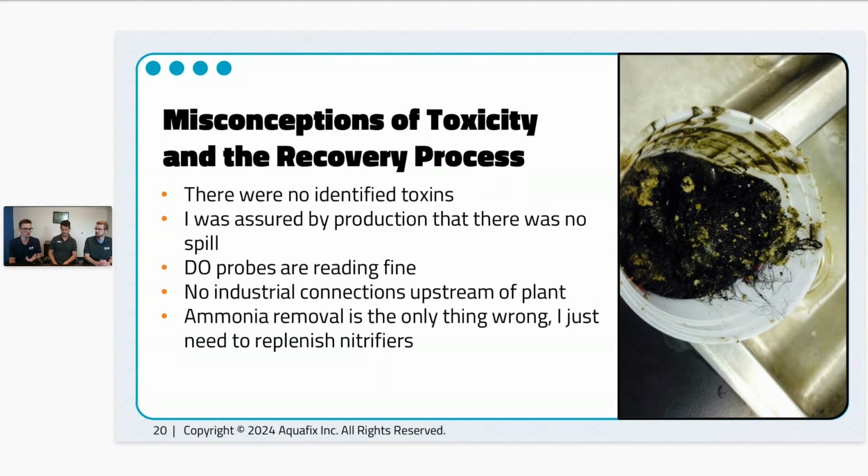It's never just one thing. These issues compound. Clogged aerator, anything around those lines can lead to issues down the road. Leads to the next bullet point, the DO probes. That being said, your aerators are there, your DO probes being on them, making sure they're calibrated, making sure they're maintained, because a misreading on that, especially in automatic systems, can lead to really bad toxic environments, which create upsets for sure. And that's what we say with both Midge Flies and honestly Nocardia foam.